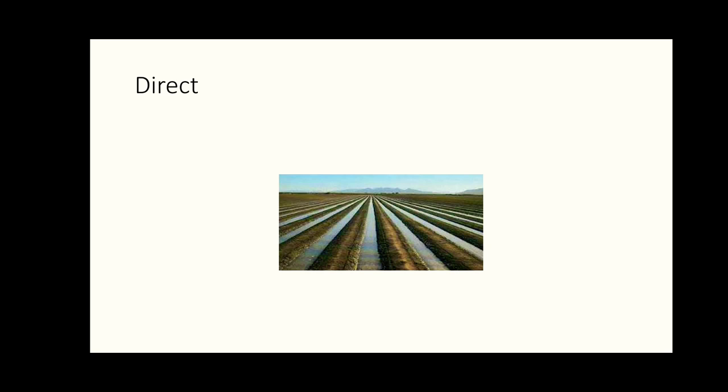For such a system, a low diversion weir or diversion barrage is constructed across the river. That's necessary. This diversion barrage raises the water level in the river, and thus diverts the water to the canal. This is called direct irrigation. Generally, the direct irrigation scheme is of smaller magnitude, because we do not have to store the water. If we need to store the water and use it, then that must be of a large scale.